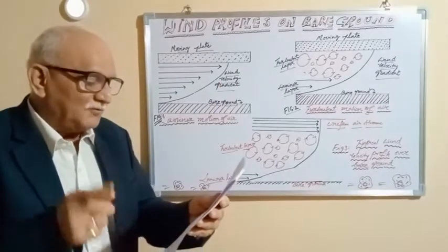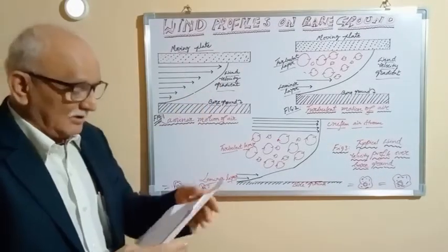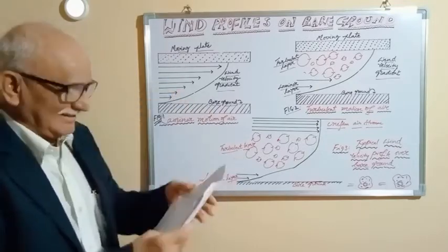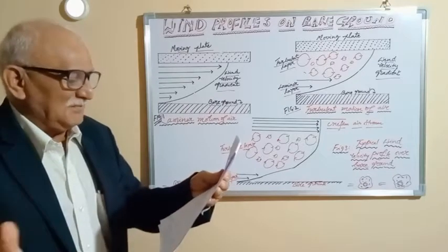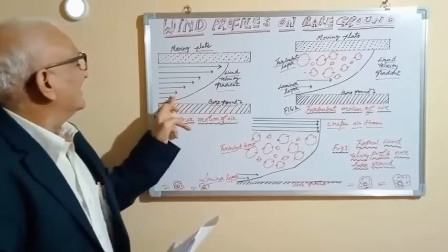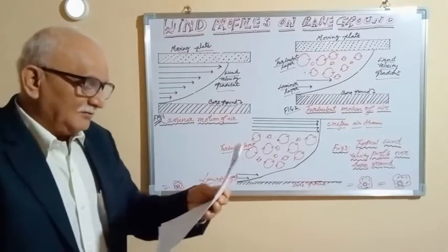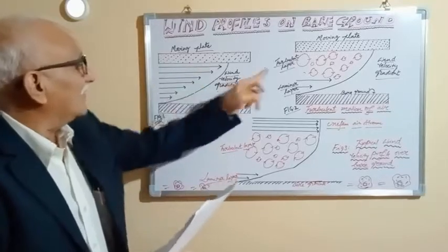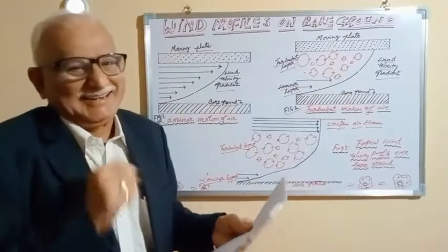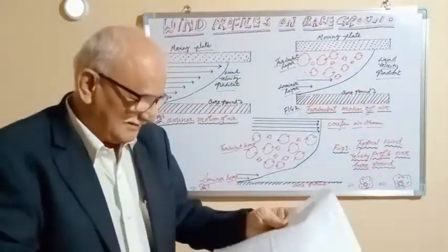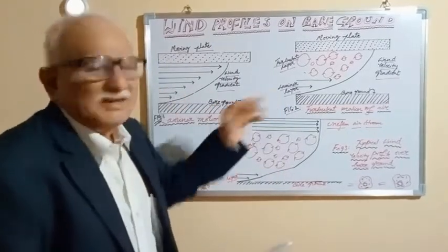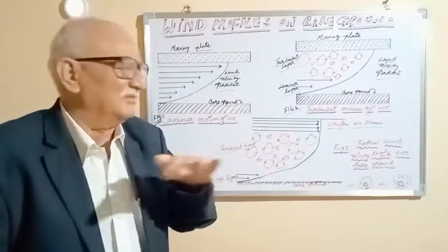Now, if the flow is laminar, in this case, the sandwich layer will have a number of thin slices of air moving with different velocities. Here is less, here is more. Now, if the velocity of the plate is increased, then what will happen? Turbulence is generated. Usually the thickness of the laminar boundary layer is of the order of millimeters, maximum centimeters, not beyond that.